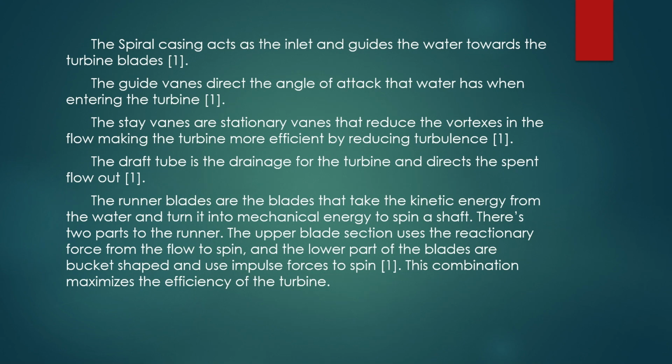So yeah, the spiral casing specifically is the one that has decreasing diameter. It's due to when you bring water through and you rotate it like that, it takes some energy out of the system, therefore decreasing the pressure. So then the decreasing diameter shoots the pressure back up and makes the water maintain its pressure to account for the energy loss of trying to turn the water from going linear into more of a centrifugal movement.